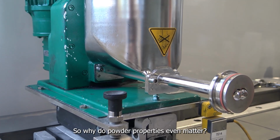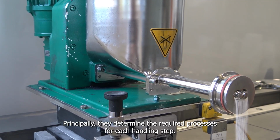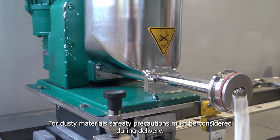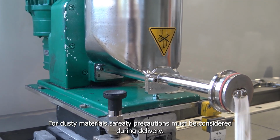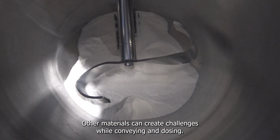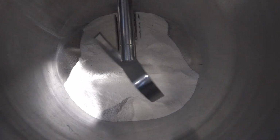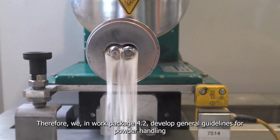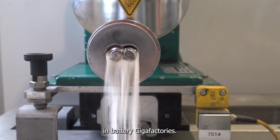So why do powder properties even matter? Principally, they determine the required processes for each handling step. For dusty materials, safety precautions must be considered during delivery. Other materials can create challenges while conveying and dosing. Therefore, we in Work Package 4.2 develop general guidelines for powder handling in battery gigafactories.